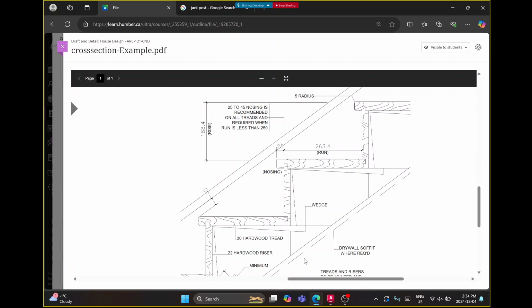If I catch them when they send me the shop drawing back and they say, yes, everything is okay, but you have the door handles on the wrong side, please revise, and I send it back to them, then it's their problem. They have to revise it, and then they build it according to the correct drawing. So it's a way of working out problems before they get built. It's cheaper to resolve a problem on paper than it is in real life. So that's what shop drawings do. And number two, it's a way of assigning liability. If the shop drawing is correct and somebody builds it wrong, you say, nope, shop drawing was correct. Sorry guys, you have to replace it. I'll work with you to make it easier, but it's your cost.